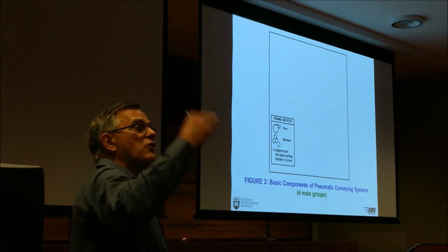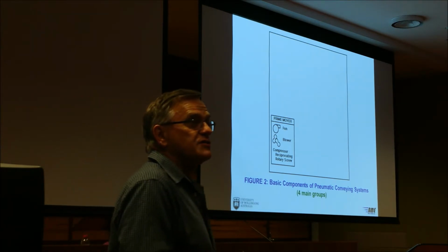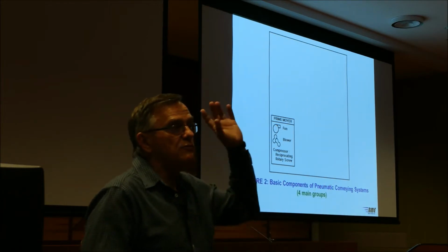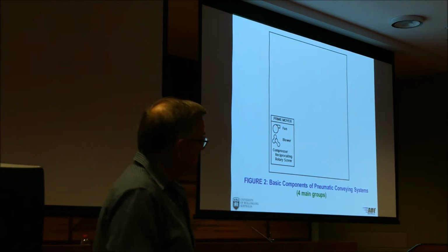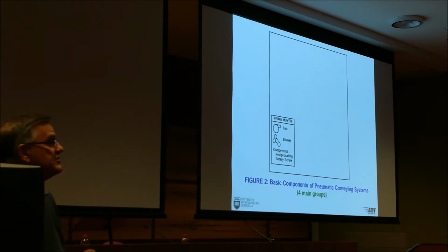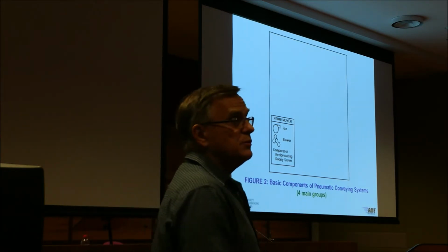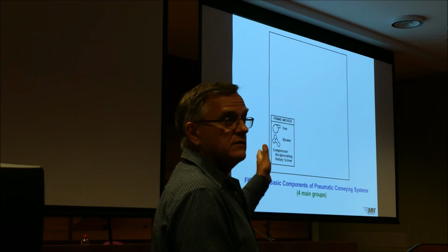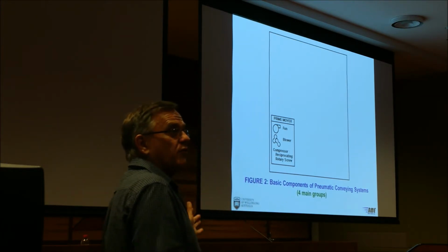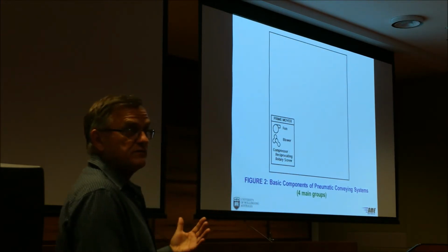Compressors go to much higher pressures, whatever you want. Typically, for a single stage compressor, maybe 300 kilopascals. Multi-stage compressor, you can go to 600, 700, whatever, thousands, whatever you need. It's very expensive to compress air. And the flow rate range is a lot less again. So depending on your pressure and flow rate requirement, we pick a suitable air mover. How you select those, all different. The terminology is all different, and I haven't got time to go into that this evening. I'll just introduce you some examples to show you the differences.